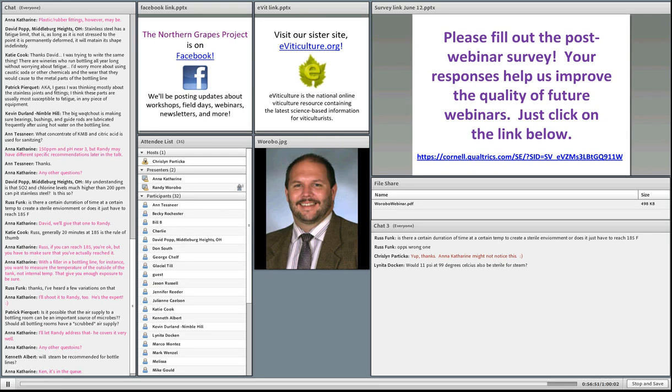Next question: sounds like pH is important for sanitizers. Do you think it's essential that wineries are able to measure pH to do a good job of sanitizing? If you're using a sanitizer that you have to acidify yourself, yes, pH is extremely important, and you should be measuring it with an accurate pH meter. You can also buy sanitizers that have the buffers built into them, if you don't want to deal with the hassles associated with it. So a buffered sanitizing solution is also a possibility.